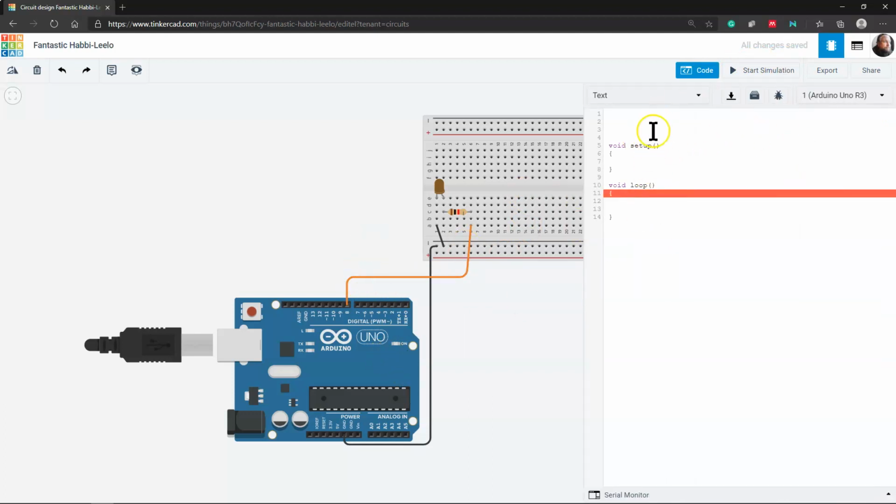You always start with this setup, and you have everything else. So the very first thing we need to do is start defining, okay, how is this pin used? And that is always done in the setup function. This is the new function you're going to use to indicate this, called pinMode. So pinMode is predefined. You can look this up on the Arduino webpage. You have pinMode and you have two actual parameters for this.